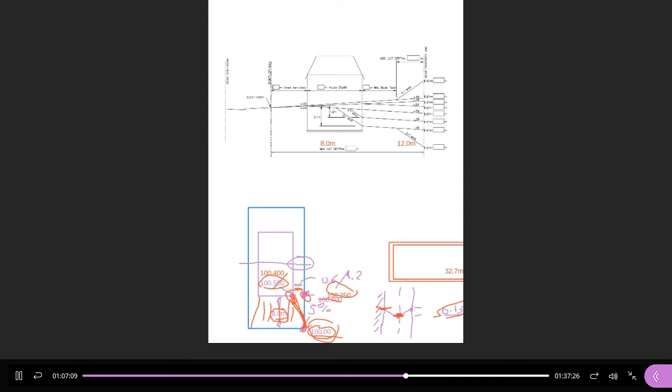Okay, so this is just an intermediate step, 0.4. So you come up 2% and then down 2%. So the final thing at the back is all we're interested in, positive. If the backyard and the front yard are compatible, they're almost the same, right? The backyard's a little bit higher, but not much. You would have a split point right there. So the side between the houses would drain to the front, and the front yard always drains to the front, but the entire backyard drains the other way.